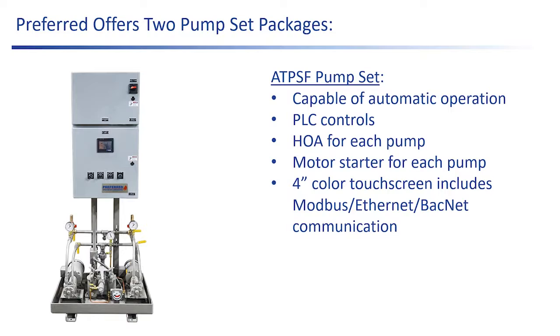This has automatic failover lead lag logic, where we'll always supply a flow switch that gets installed in the discharge of these pumps. And if a pump is commanded to come on, that flow switch has got to open within a time delay limit. Otherwise, we're going to sound the alarm and start the other pump.